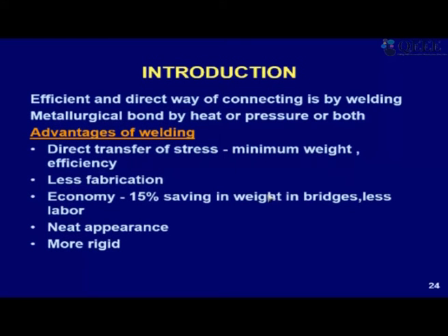Now let's proceed to welded connections. So there are many advantages of welding. The basic advantage is we don't have to drill a hole, so we are not cutting or reducing the member cross section. So that is a major advantage. Direct transfer of stresses. So we are not adding any extra plates, so no weight, no cost, etc. So there is also a lot of cost saving and neater appearance, and it gives a very rigid connection. So these are the basic advantages.